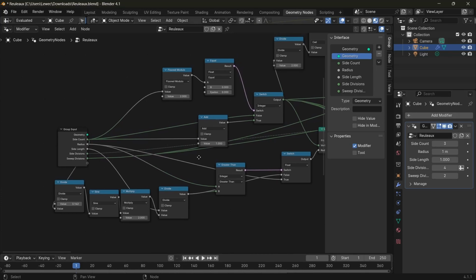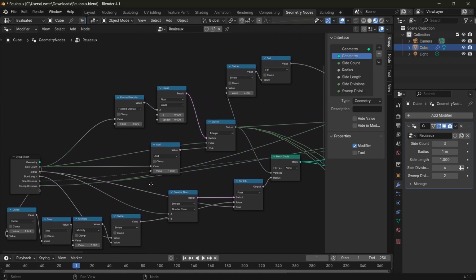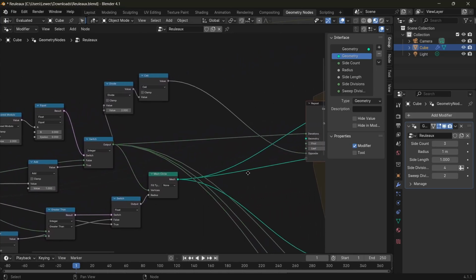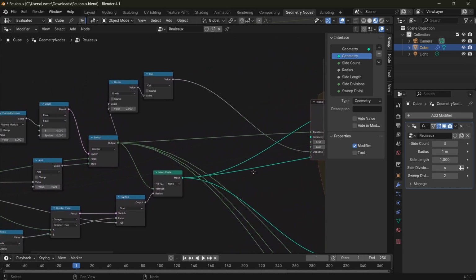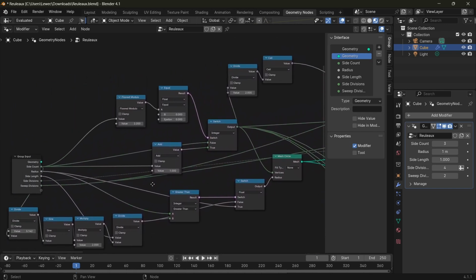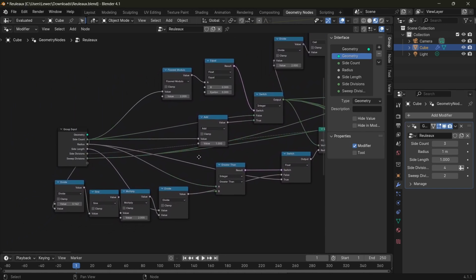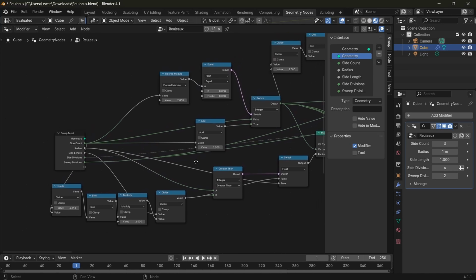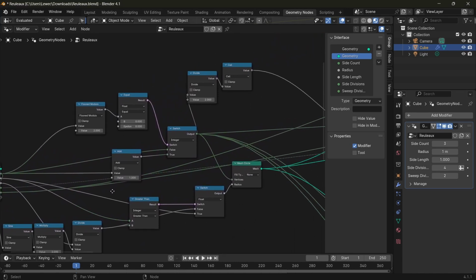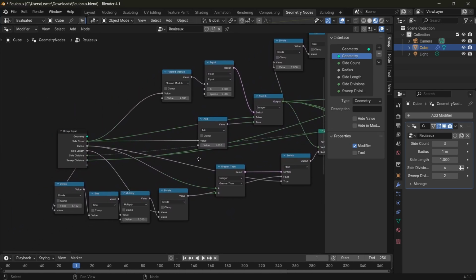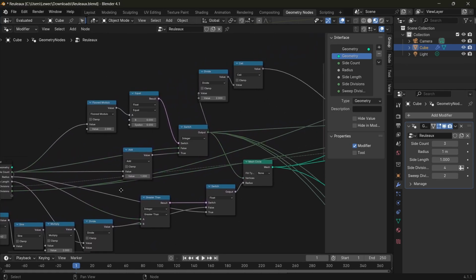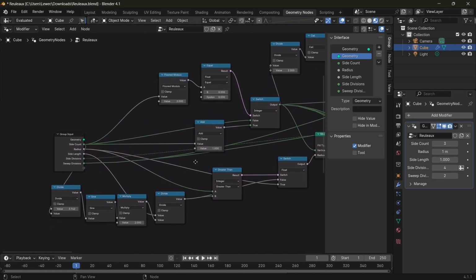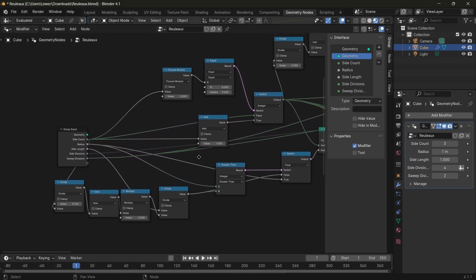The first step is creating a mesh circle, also known as a regular polygon, for the arcs to be built on. The circle is created with a number of vertices equal to the side count. If the side count is even, 1 is added since a Reuleaux polygon must have an odd number of sides. Then it checks to see if a polygon of the given side length and number of sides would have a greater radius than the input radius. If so, it uses that radius, and if not, it uses the given radius.